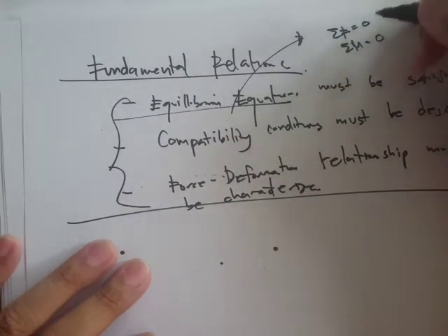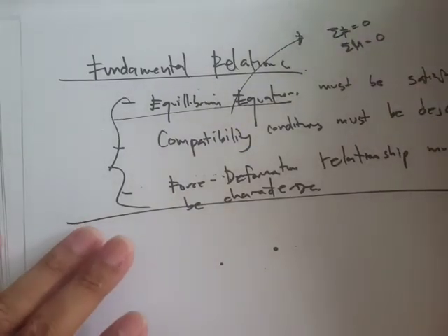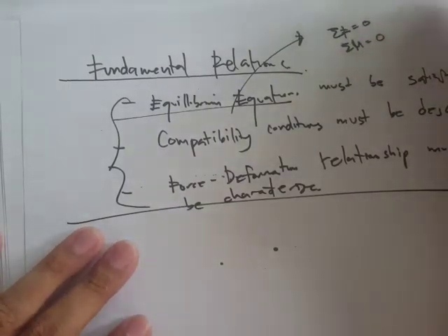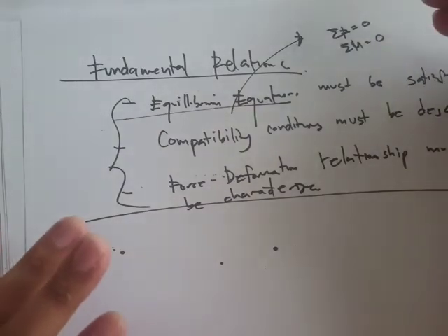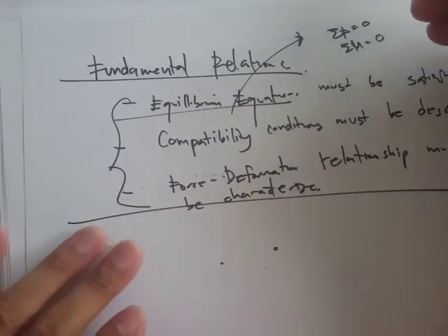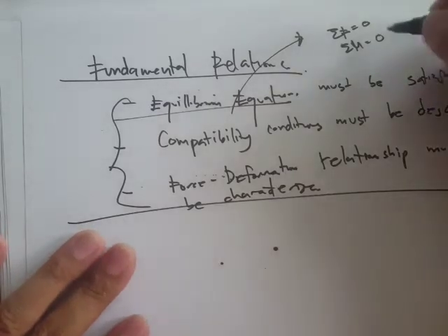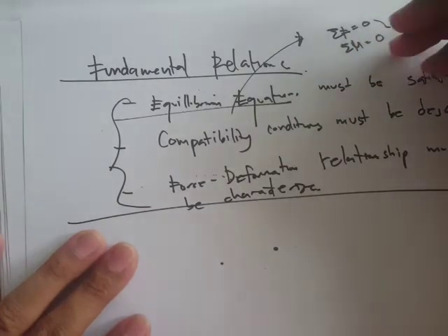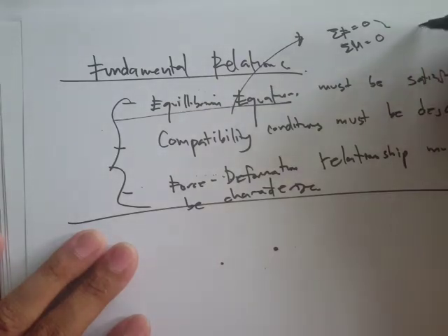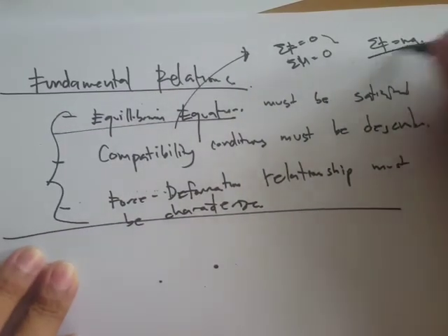That's the point of equilibrium. Equilibrium doesn't mean that it's not moving, although in structures that's the case. But a more precise definition of equilibrium is that there is no acceleration. So summation of force equals ma, if you recall Newton's second law.